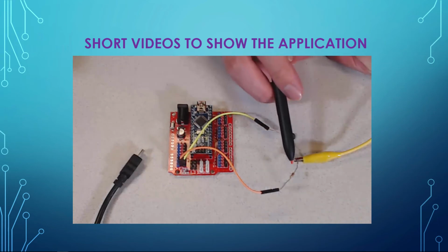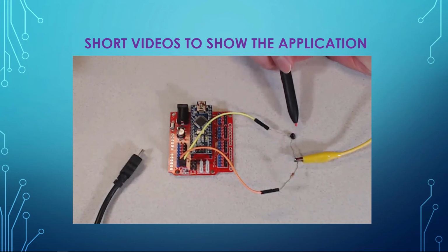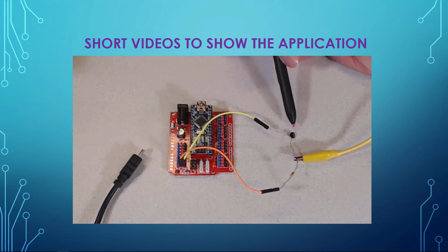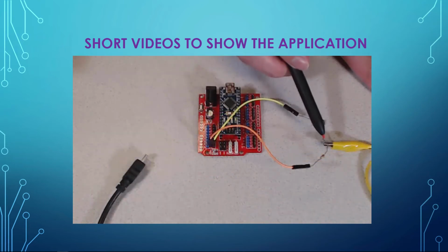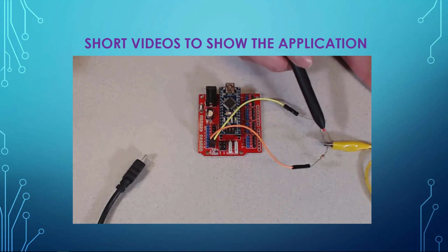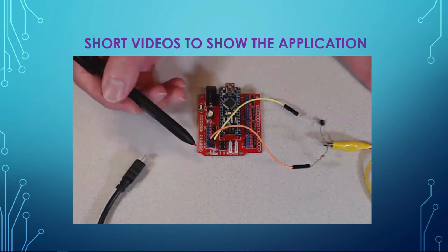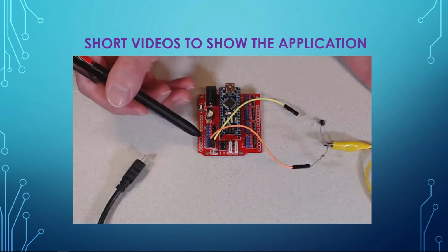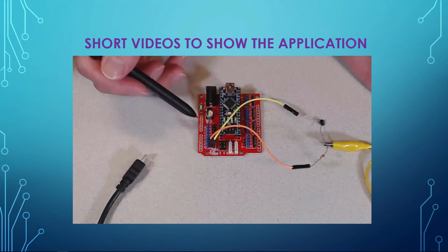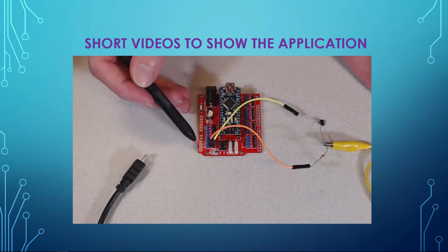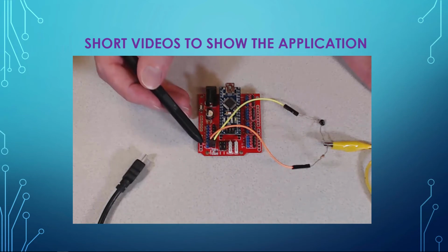With this setup, we have a 10 kilo ohm resistor here and a 10 kilo ohm temperature sensor. At 25 degrees, it has a resistance at around 10 kilo ohms. To read the voltage output of the node here, we need to use the Arduino's analog read pin. They're over here. These pins are denoted with letter A before the numbers. When you set the Arduino to read from, for example, this pin, it detects the voltage and returns a 10-bit value that needs to be processed.